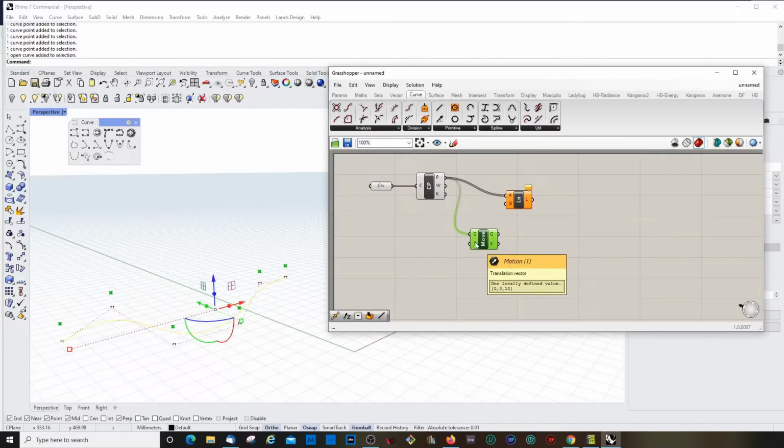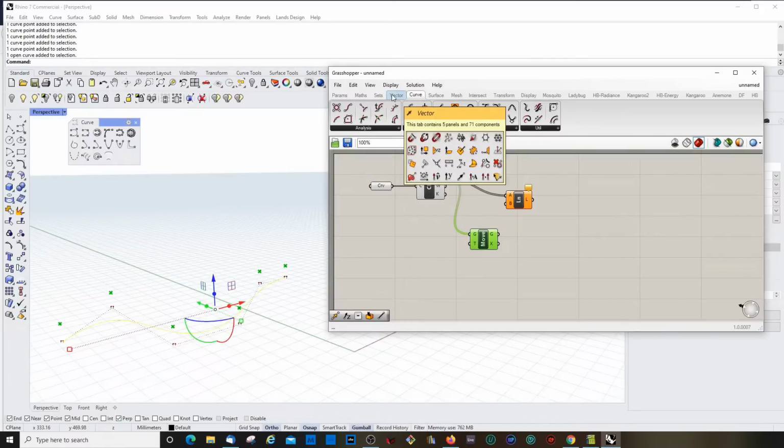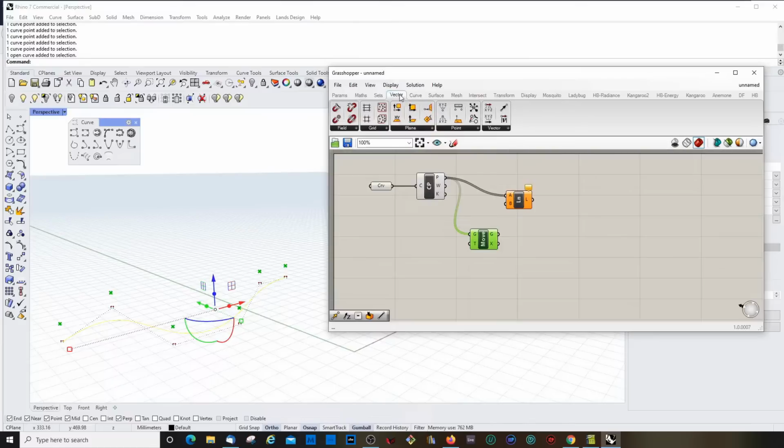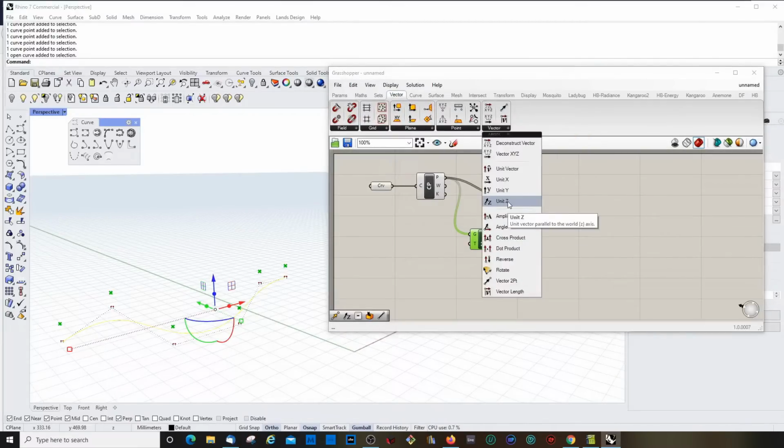If I hover over this, you can see that there are already coordinates in it, and it translates the current position of the point. It moves the points vertically by 10. Of course, you can put another vector in here. In order to make that more useful, we can go in here and say vector set in the set direction.